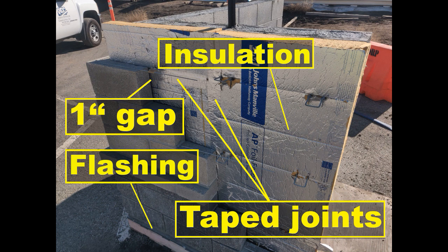Apply insulation in parallel courses with vertical joints breaking midway over the course below and in moderate contact with adjoining units without forcing. Cut to fit neatly against adjoining surfaces. Tape or seal the joints between the boards. Insulation will act as air barrier surface and all joints and gaps shall be sealed.